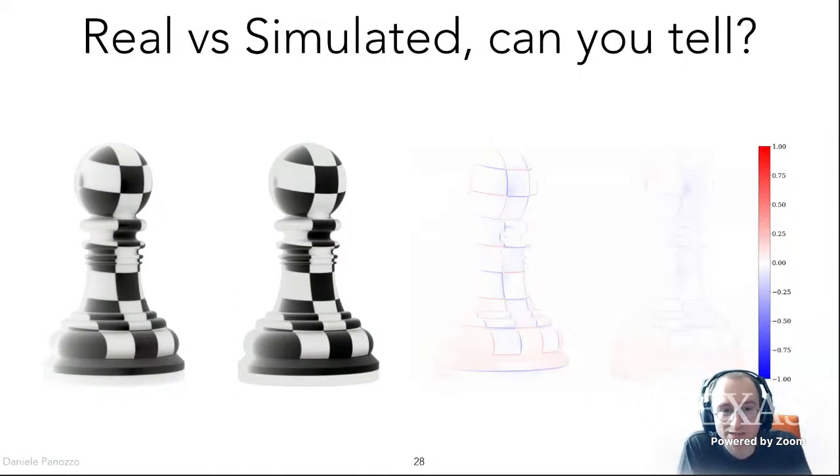The other thing is that the actual procedure you use to calibrate is important. Usually, relying on just a few images of a checkerboard is not enough. So what we ended up doing here is to have a robotic stage that allows us to get hundreds or thousands of images and then average it all. This gives huge advantages in the accuracy that you can get if you're willing to invest more time to calibrate.